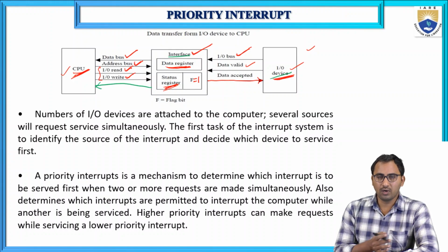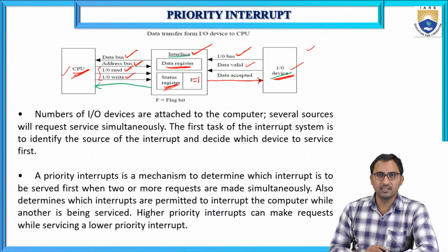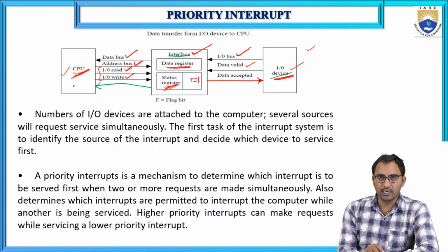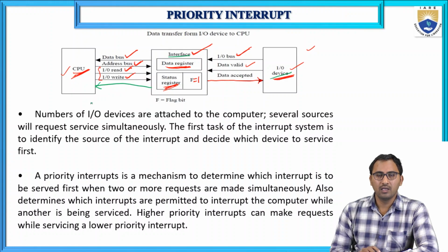Before receiving the interrupt signal, the CPU is busy executing its important programs. Whenever the CPU receives an interrupt signal, it stops the currently executing program or task, and stores the return address in the stack memory.